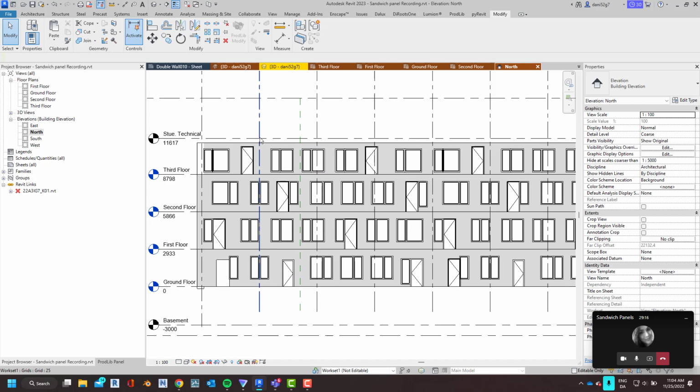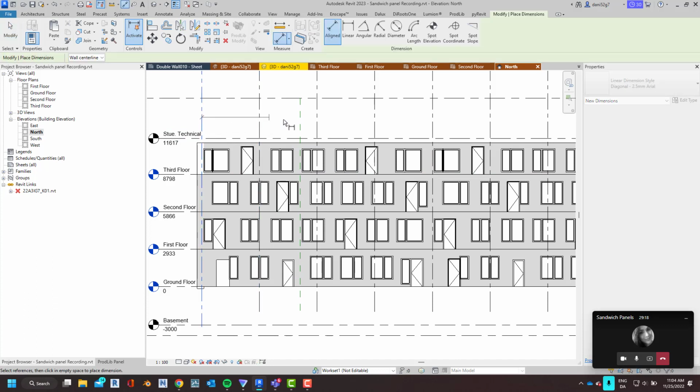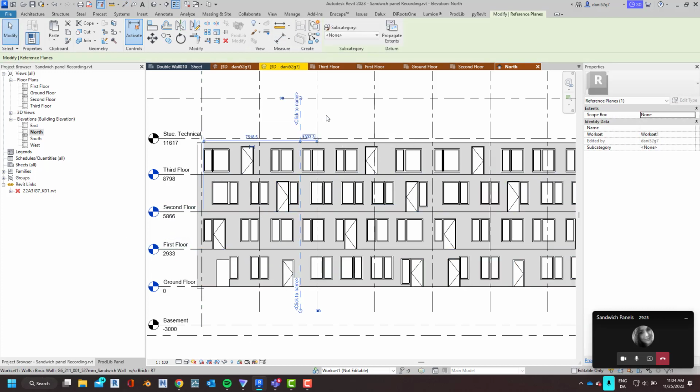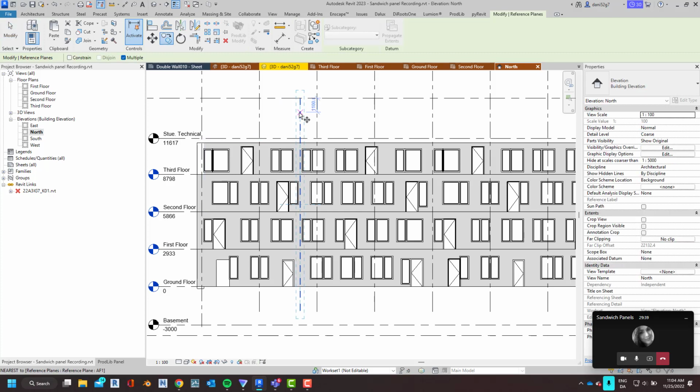That looks pretty good. Let's dimension this from the edge to here. That's about 7.6 meters, so that fits within our limit. Then what you're going to do, very important, is label the first one. You're going to do architectural facade, for example, whatever coding method, 1. The reason you do this is because when you copy this over to the next split location, which let's say is here, another 7.5 meters,